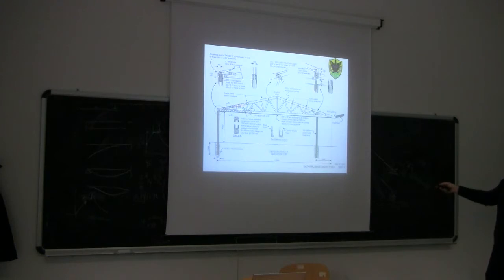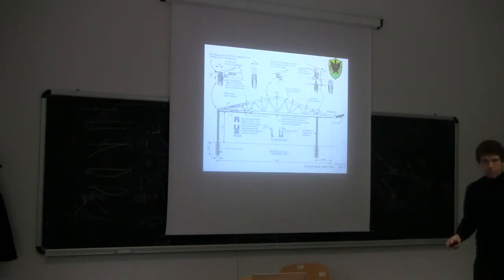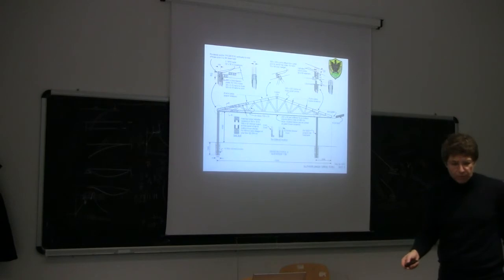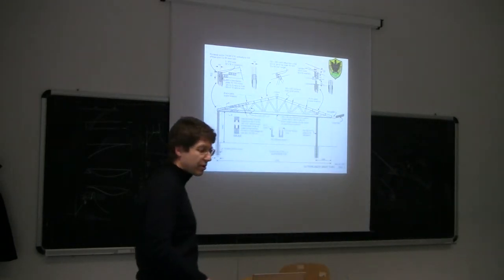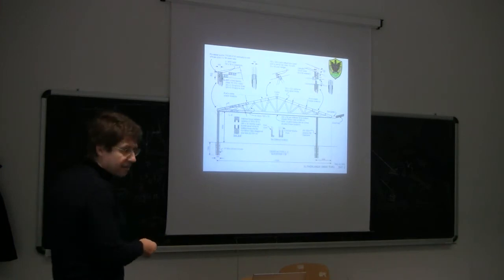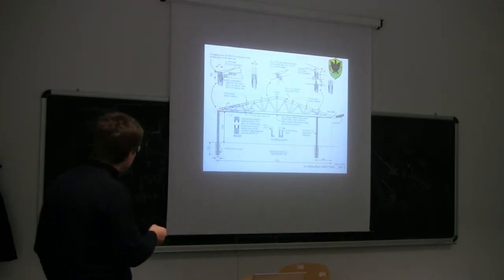So we have the top and the bottom chords, and then you have the diagonal member. If you remember, we said last time that when we model a system like this, it's important to make sure that the axes of our static scheme are basically coincident with the axes of the top and the bottom chords.